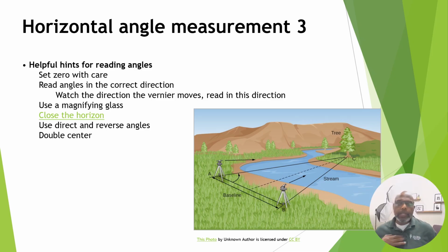So looking at the horizon angles and measurements, some of the things we're looking for is making sure the equipment is installed correctly, that it is level, that it is balanced, that the scale on it is set, but also checking when you're taking readings that you're taking multiple points to verify that things are correct.